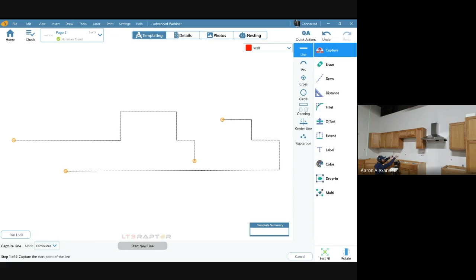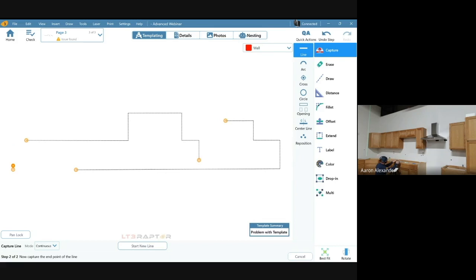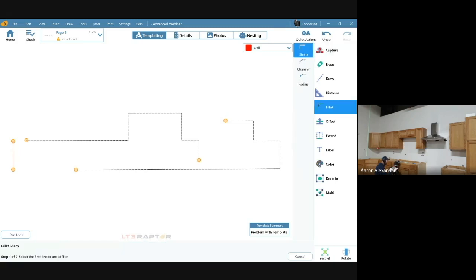Typically, I believe you guys are going to install the long wall first. And so we could pull a half-inch out of that corner, and then on this left wall, we pull that 1.25 inches plus material, plus glue or whatever we're going to do. So the left piece butts into the face of this piece. So we really just need to know where that wall's at, and we could pull it in, you know, 3/4, half inch, even a 1/4 inch, all that would work because we're going to cover it with our left piece, right?